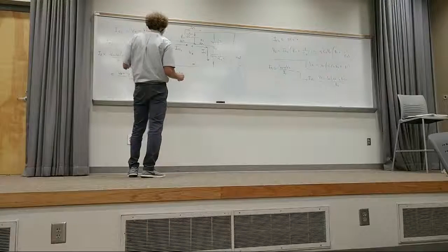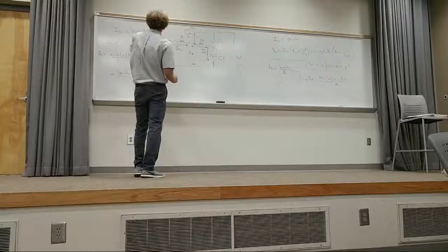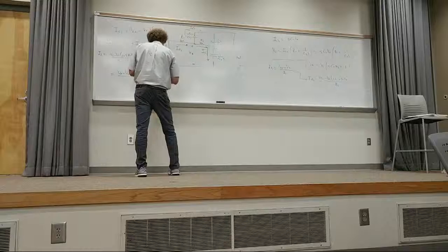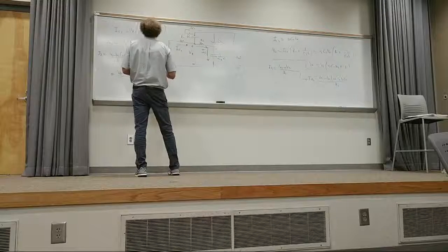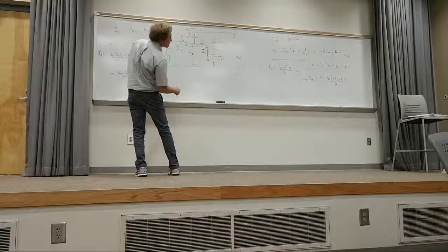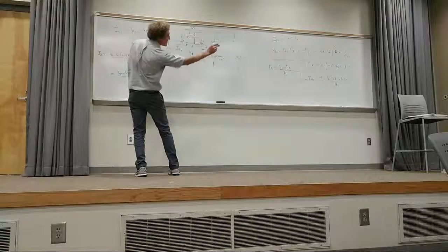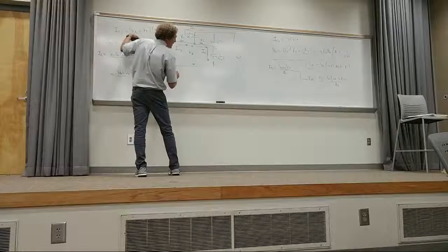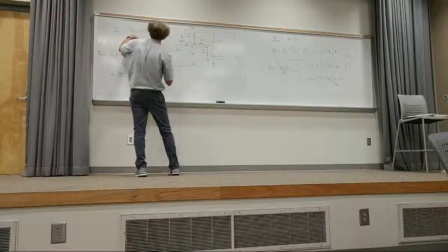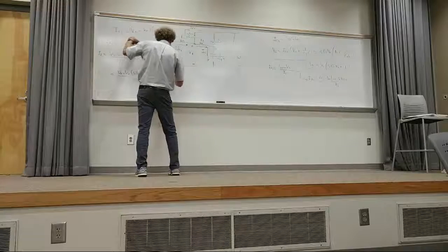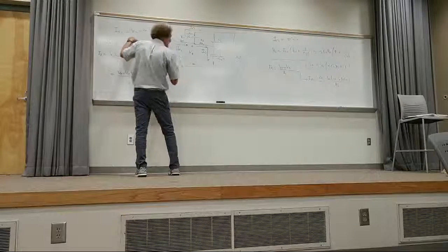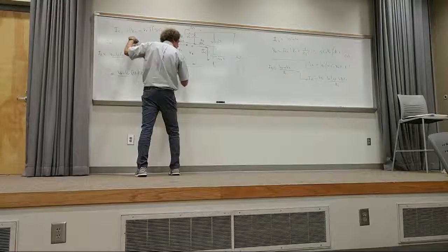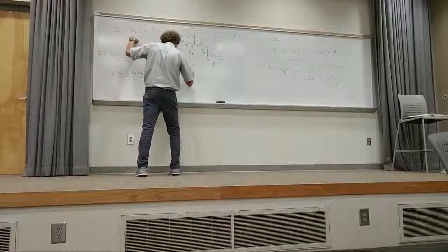now it's equal to IC1, which is here, which is V2, pardon me, V2, and V2 is, where is V2? I wrote it somewhere. Over there, right? See it? Class? Yes. V2, so I'm going to put V2 here, which is V naught. I got V naught here, so I'm going to factor out the V naught. And I get 1 plus S C2R2, right?